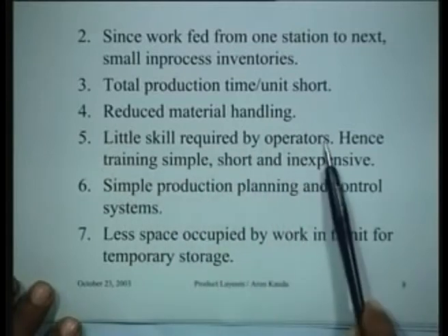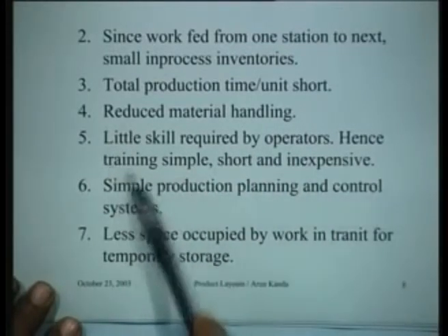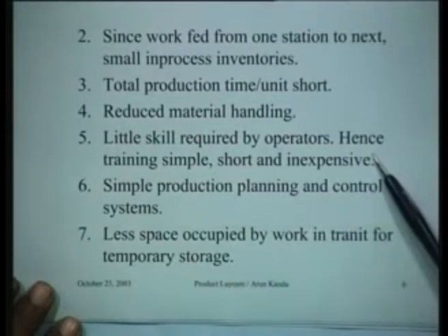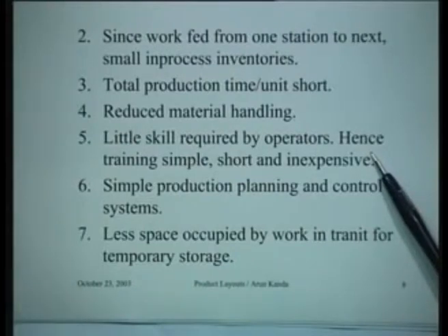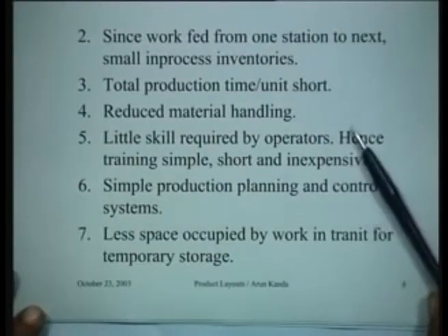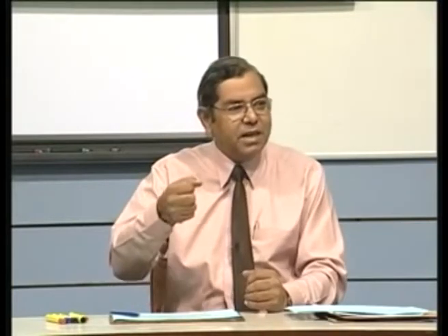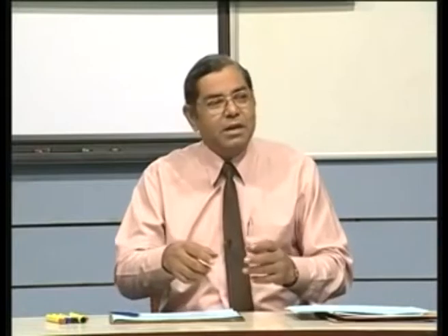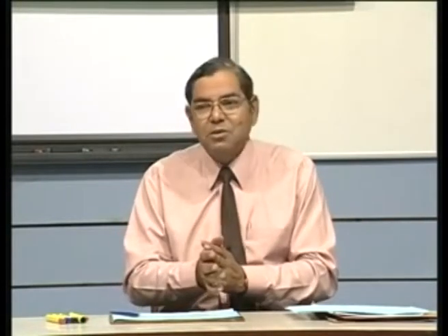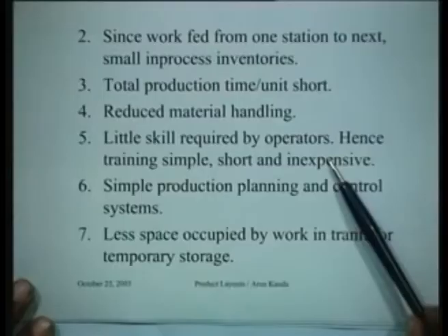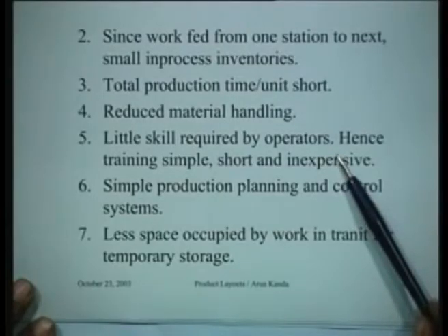Little skill is required by the operators. Hence, training is simple, short, and inexpensive. Why? Because the operator is doing very, very simple kinds of things, right? His job might be to pick up the piece from here, operate a foot pedal where it is held, and then take the compressed air and do some blowing, and then probably release it and send it to the next operation. So he has to do a couple of things which can probably be learnt in half a day. So training is quite simple and inexpensive, unlike the training for a process layout.